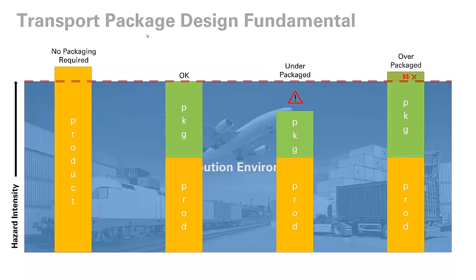So if I can drop my product without any packaging from 48 inches, and I prove that on a shock machine, but in the supply chain I only expect it to ever be dropped no more than 24 inches or 1 meter, then you use that type of information to say, I guess I don't need protective cushion packaging, using both pieces of that information. So again, the relationship is important to understand.